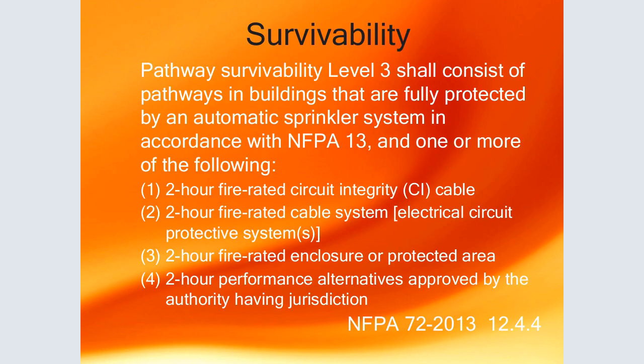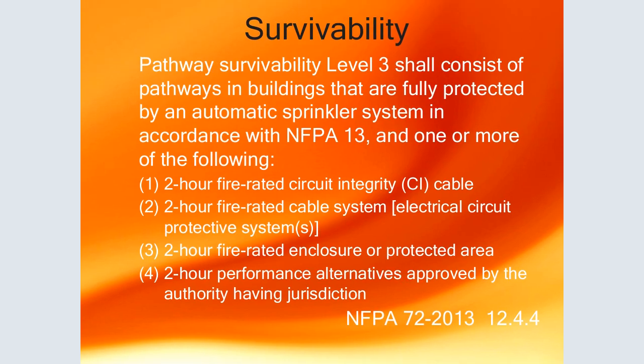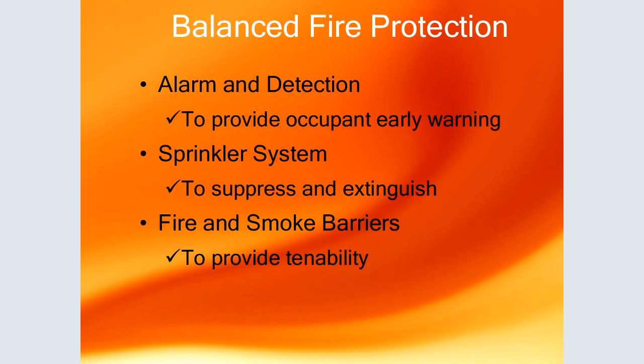Pathway survivability level 3 shall consist of pathways in buildings that are fully protected by an automatic sprinkler system in accordance with NFPA: a 2-hour fire-rated circuit integrity cable, a 2-hour fire-rated cable system, a 2-hour fire-rated enclosure or protected area, or a 2-hour performance alternative approved by the authority having jurisdiction.